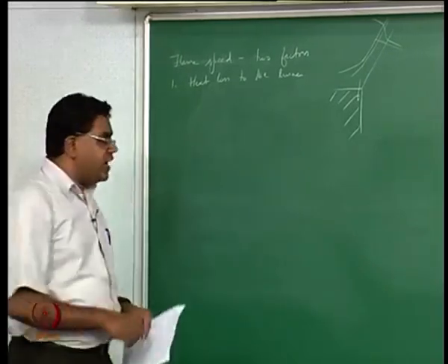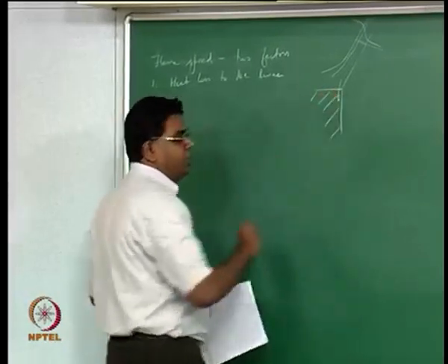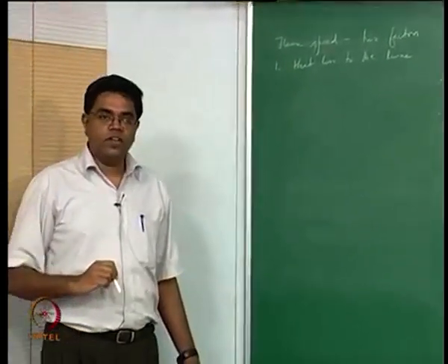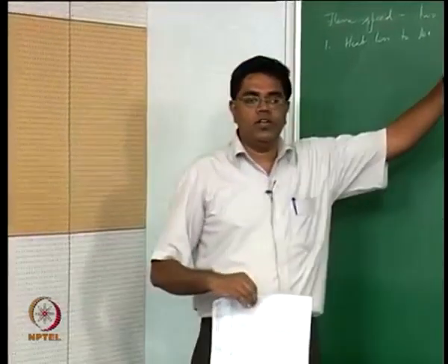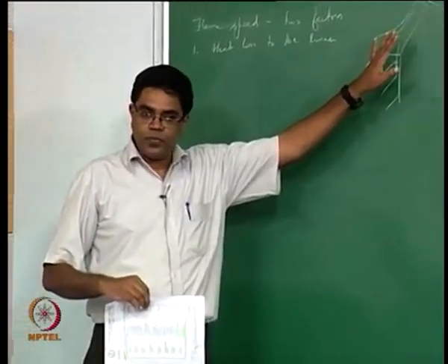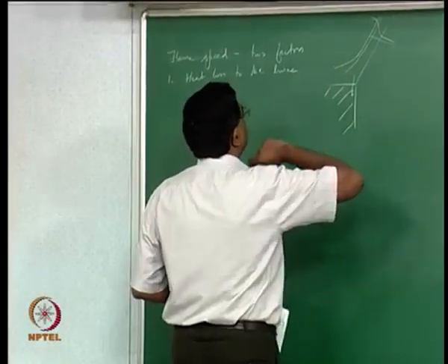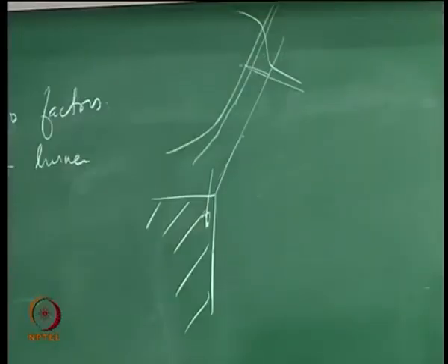But the moment the reactants are not the ones that are going to get heated up anymore, that's not an adiabatic system. So obviously then the local flame speed should decrease, right? So the flame essentially becomes a lot thicker, and the flame speed progressively decreases as the flame is held closer and closer.